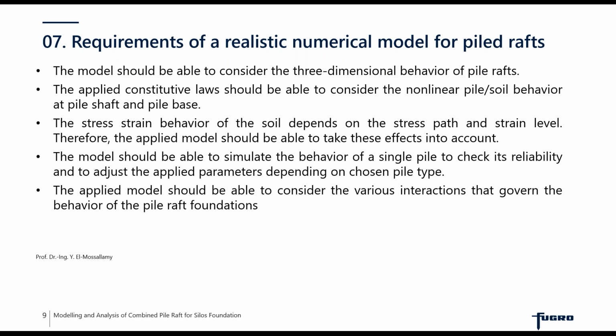So you can adjust if needed, or you can be conservative by considering a sufficient factor of safety on the applied design parameters. And finally, the 3D model which you have considered should be able to consider the various interactions which govern the pile raft foundations.